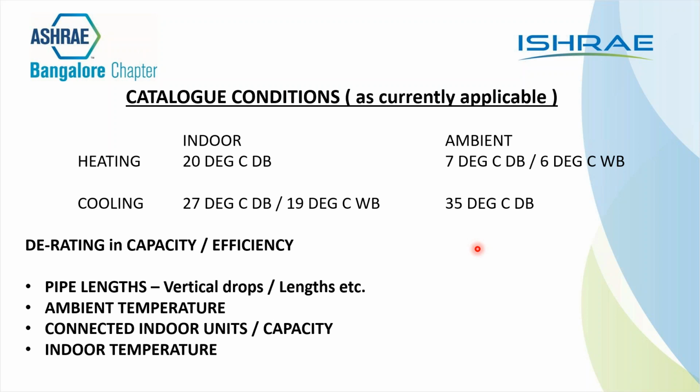No, you give me a 10-ton indoor unit, you give me a 5-ton outdoor unit, and say I will manage, you don't worry. It doesn't work that way. There is a technology that happens, and when you consider it technology-wise, you have to consider it the right way. These are some of the ways you can calculate the right diversity, and what needs to be considered and when is very, very important.